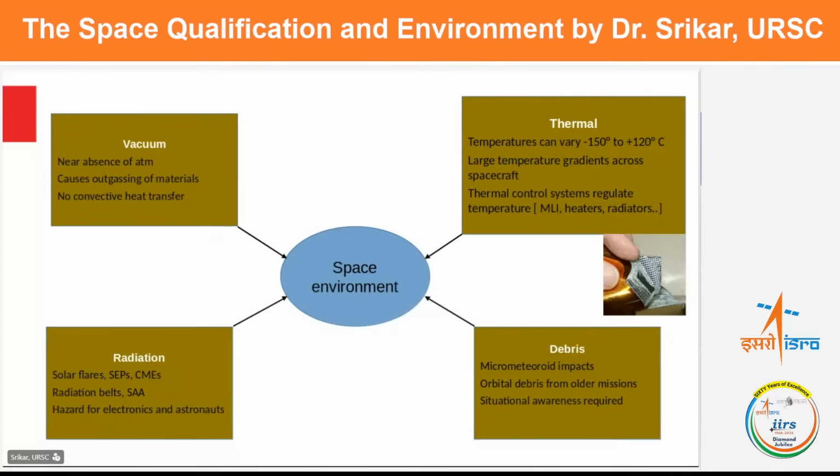As I said, in space we are almost looking at vacuum. It's a very high degree of vacuum, at least beyond 10 to the power minus 12 or even minus 15 millibar. We cannot easily get such kinds of vacuum on the ground. We have very high vacuum and ultra high vacuum systems available, but replicating space is a very tough task.